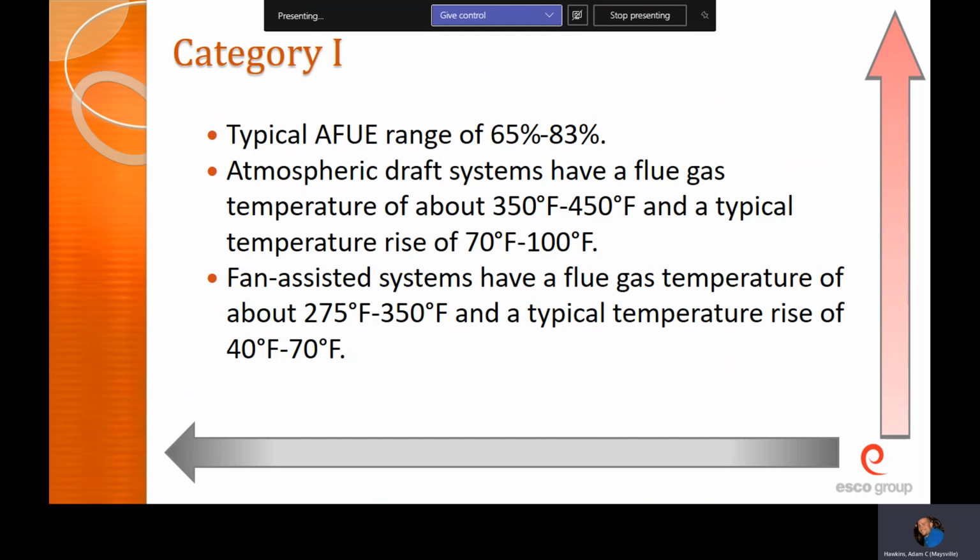And so the closer you get to 100, the more complete your heating efficiency is, to where you're using almost everything you can. You're not going to get it to 100, but a lot of the furnaces they're running now are running 97, 98%. So they're getting as close as they can, but you still have to have a little bit of waste because you have to have a flue. You have to have a vent to get rid of the stuff you don't want.